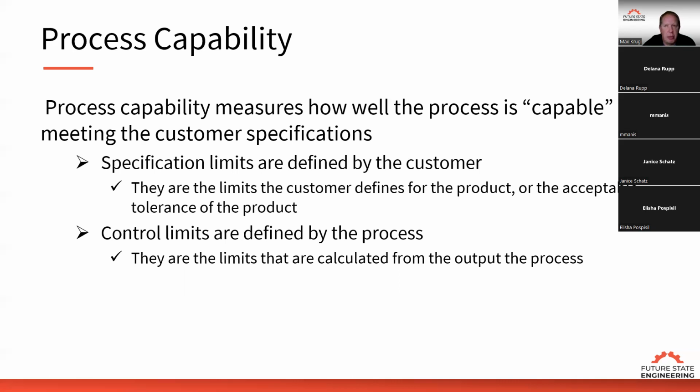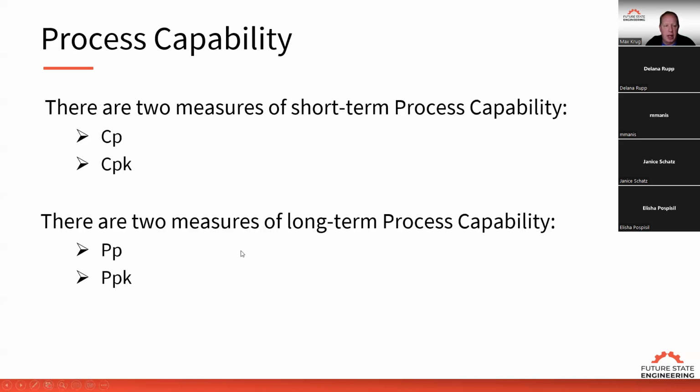Now, when they fill the beer in the can, how well are they able to fill it to 12 ounces? Okay, so what does the process actually hold? So maybe the process can hold a tolerance of 11.8 to 12.2. Okay, so we never have a can less than 11.8, and my tolerance is 11. Okay, that's acceptable for me, so that's capable. So what we're doing is we're comparing those limits that are defined by the customer to the limits that are defined by the process.